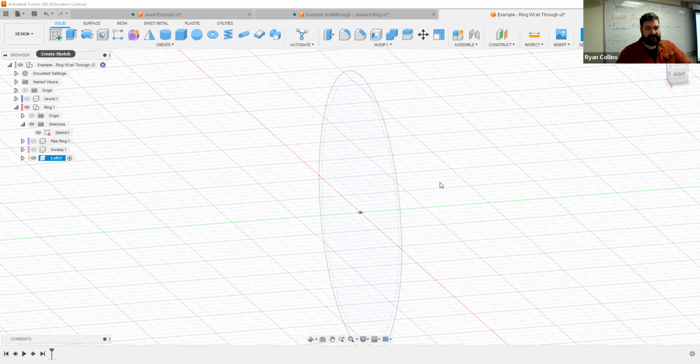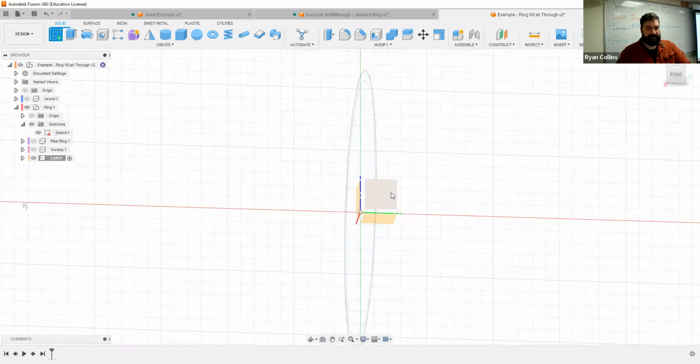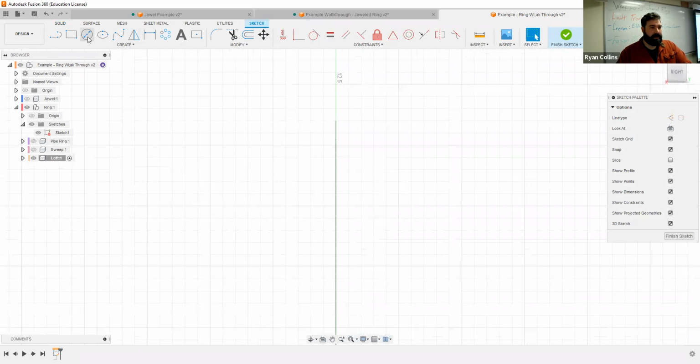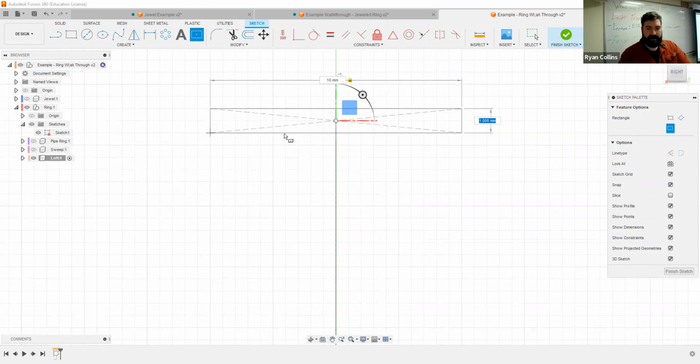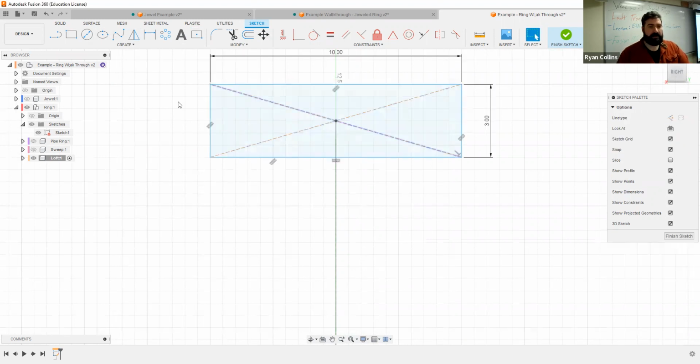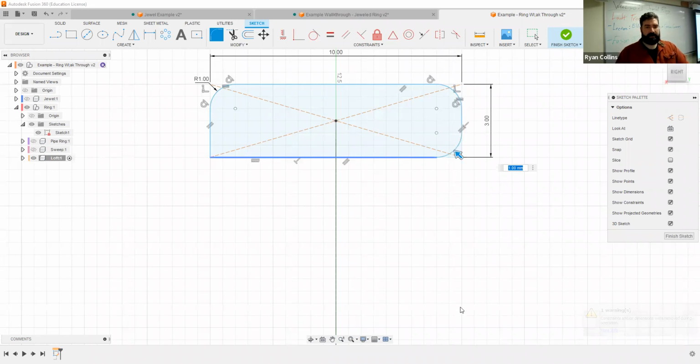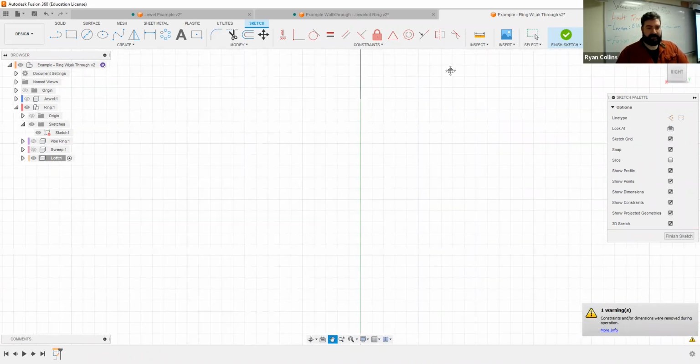So I can create another sketch again on the perpendicular plane here. We'll do one at the top, and that one will be a center point rectangle that is a little bit larger. Let's say, sure, 10 millimeters, which just seems huge, by 3. Okay. And I do want to round the edges because that would be a terribly uncomfortable one. Say 1 millimeter fillet. Don't hit enter. Keep selecting around, and it will share all of those. Okay. Now we're good. And resize, go to the bottom.